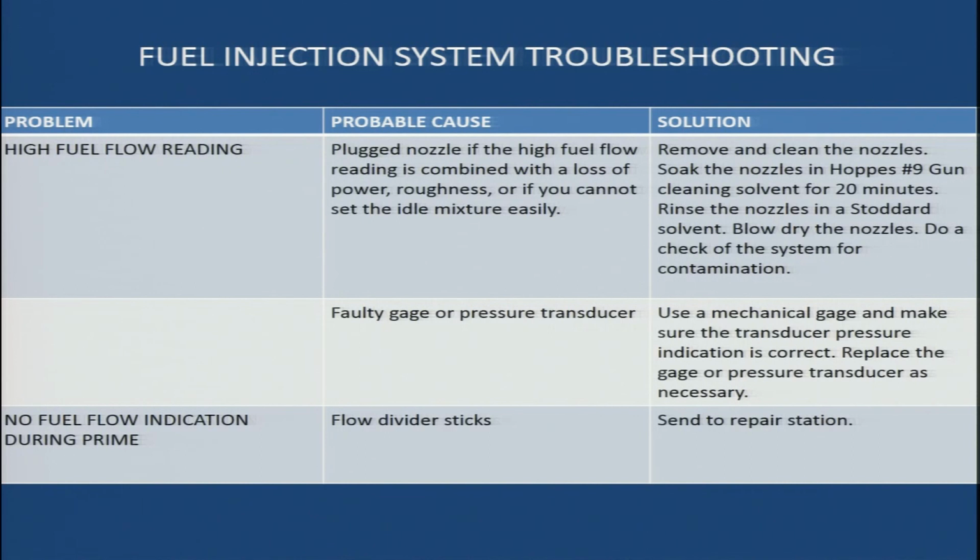So in case we are not able to set the idle mixture, we are experiencing power loss, we are experiencing roughness of engine operation, then the nozzles might be blocked.